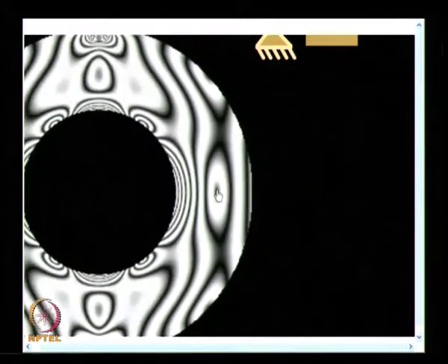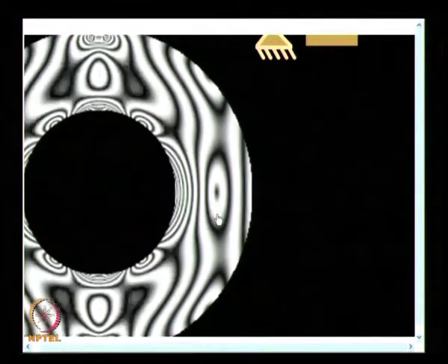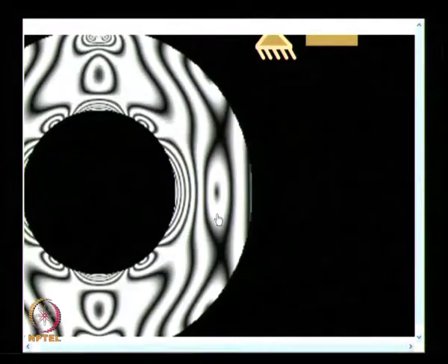After me telling you this, you observe it. In this zone, fringes come out of it and then they become denser and denser, and this remains as such. We have had enough clue earlier, when we discussed the zeroth fringe order. I said the zeroth fringe order does not move even when the load is changed, is it not?